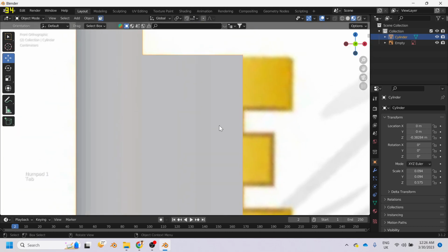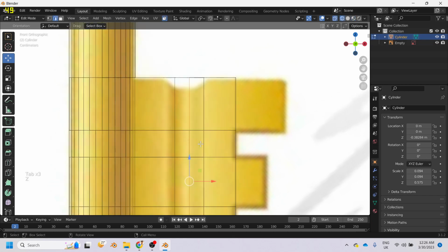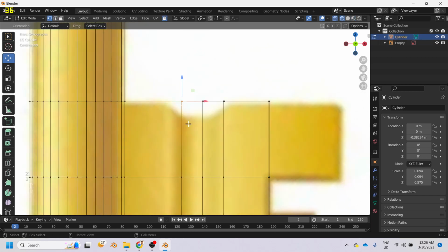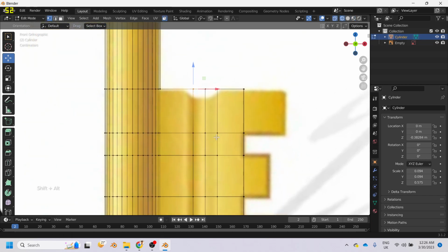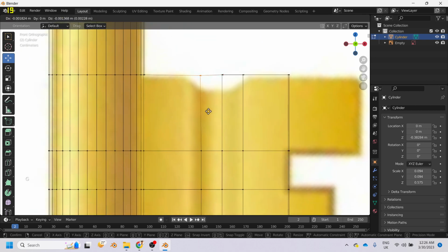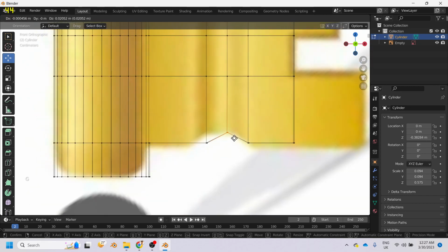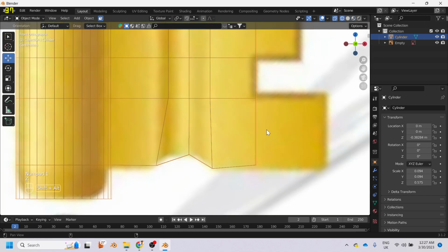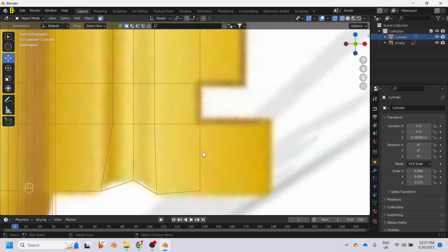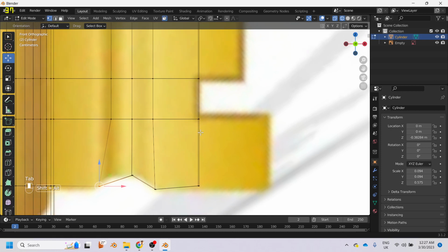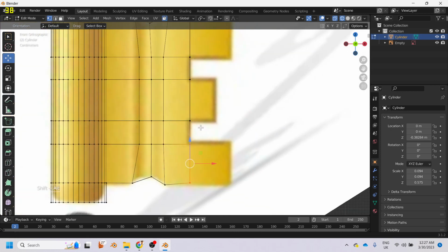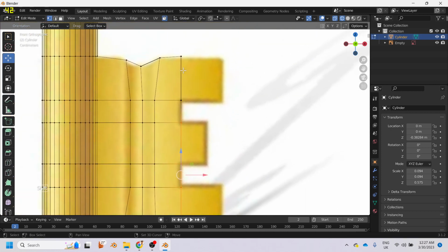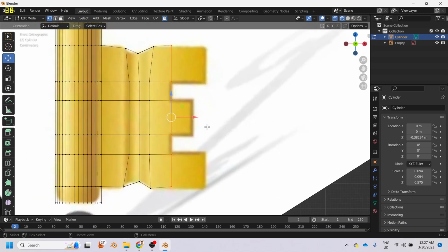Right now we are going into the edit mode, select edit mode, and edges. We have to play with the edges so that we can make it more like we want. Okay, so I'm just creating this as we wanted. Now what I have to do is select this area. For that I have to be in edit mode, select this part, and this part, and press E.